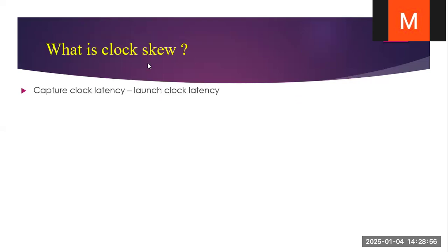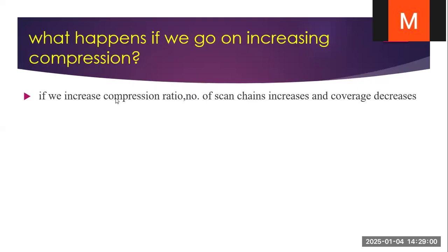What is clock skew? Capture clock latency minus launch clock latency. What happens if we go on increasing the compression? If we increase the compression ratio, the number of scan chains increases and coverage decreases.